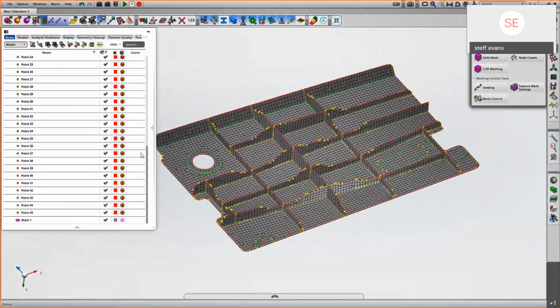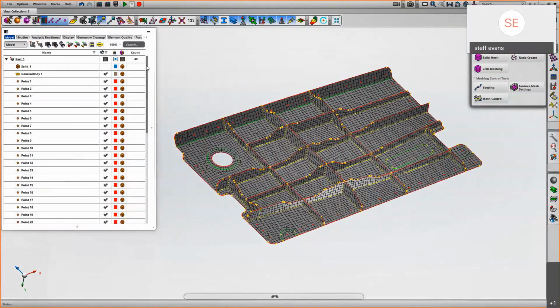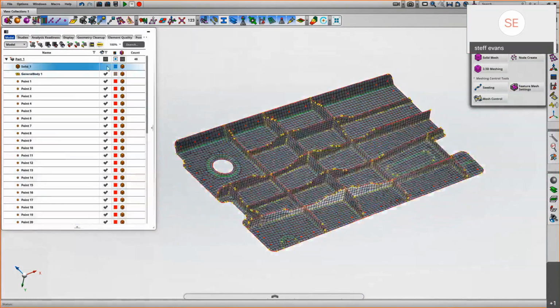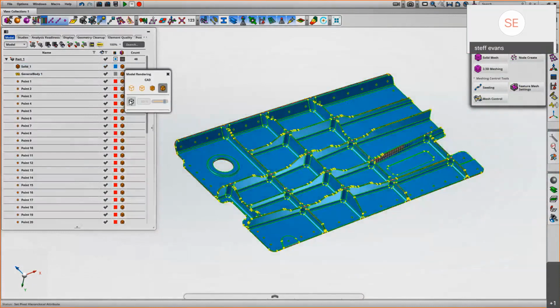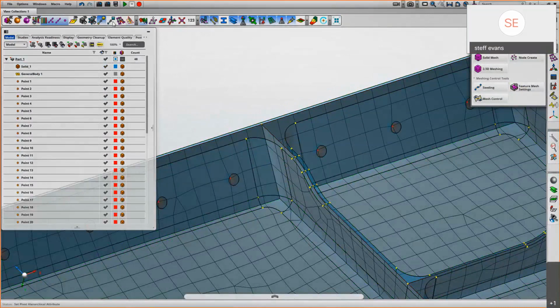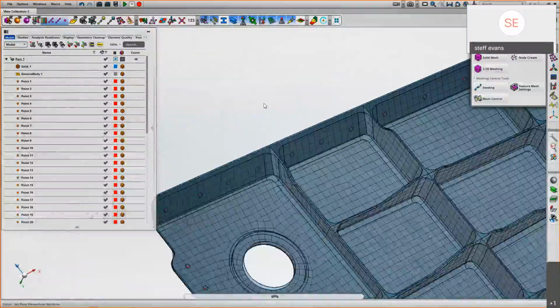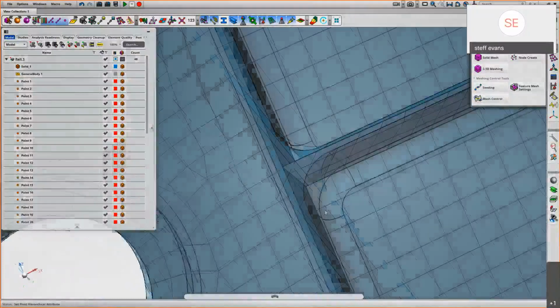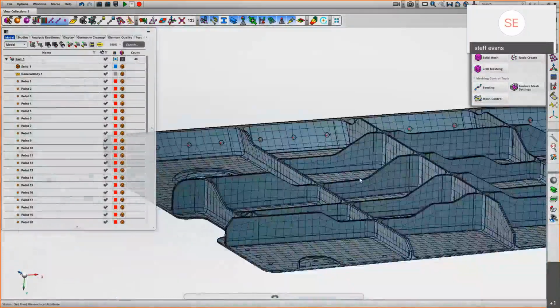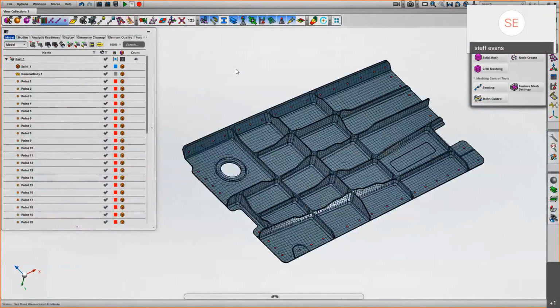Okay, so we've got the shell mesh fully defined. We're happy with the quality. We've got all the elements tied together. Again, we've got the transparency, so we can show the mesh with the underlying solid in there. We've idealized the mid-surface in some of these thickness regions where we've got step geometries, but you can see the type of thing that's defined in there.